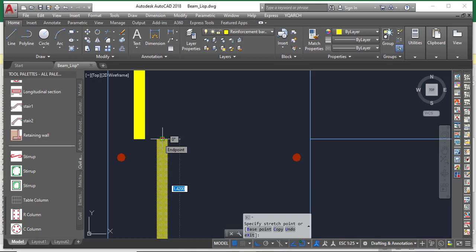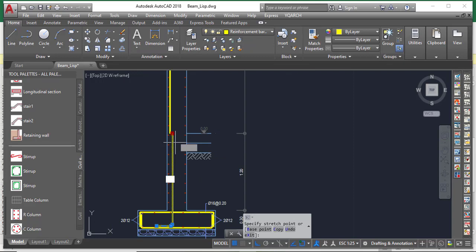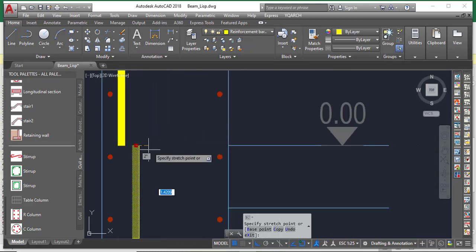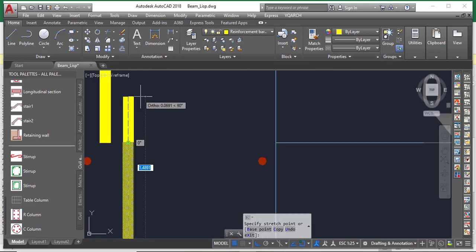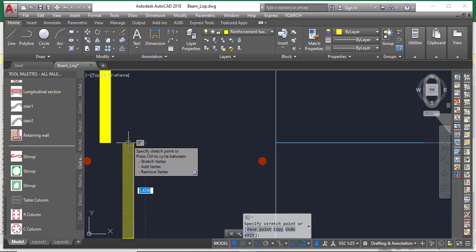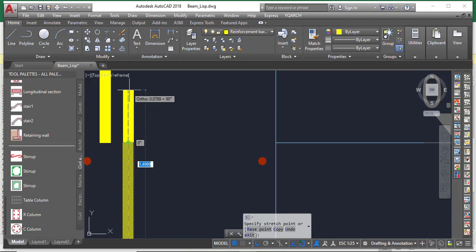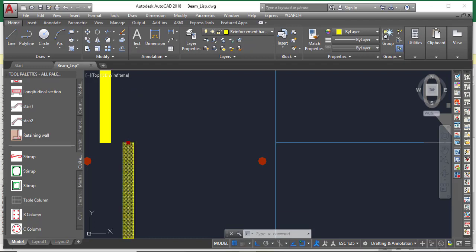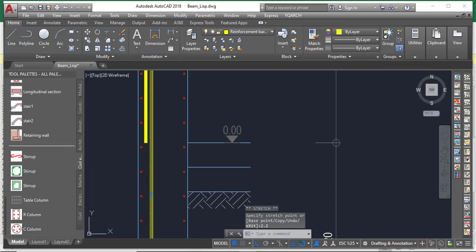1.42, which tells you that the extension you are making is actually counting from the bottom, not from this point where you started it from. So you should be careful about how you insert the number. So if you want your lapping to be 0.8, all you need to do is add that 1.42 origin to 0.8, and that should be equivalent to 2.2. So when you take this upward, just type 2.2 on your keyboard and then enter. Then it is going to elongate by 0.8.